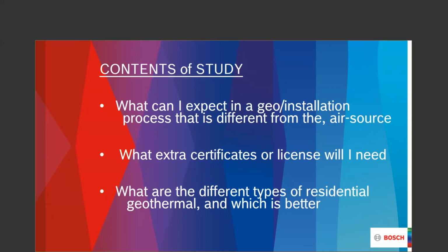Okay, so here are the three things. You've got to have water quality. Well, what do you mean, water quality? That water quality needs to be a certain pH number. We would love for it to be neutral water. Here in Oklahoma, we have pretty hard water. There are some areas within 30 miles of my house where the guys that have electric hot water tank type units are cleaning those things out three to four times a year because the water is so hard. So here's the deal about an open loop: water quality.